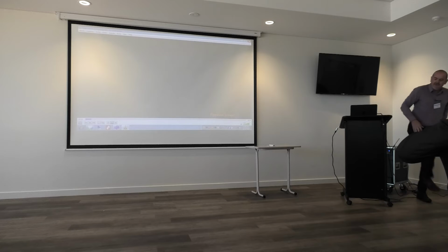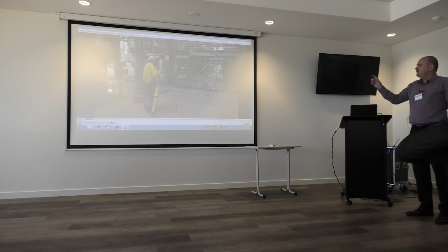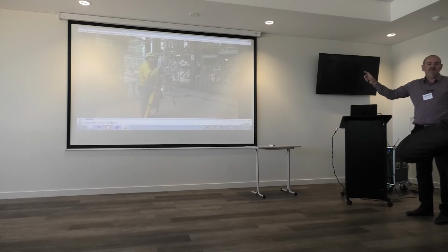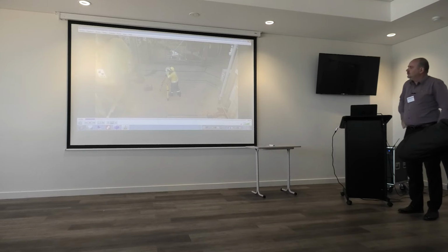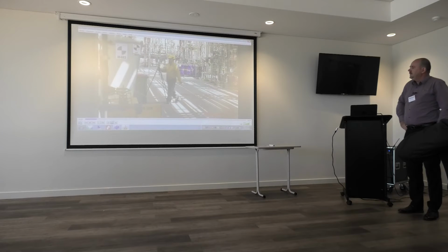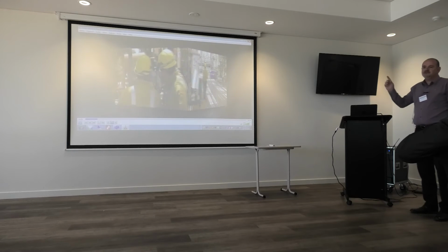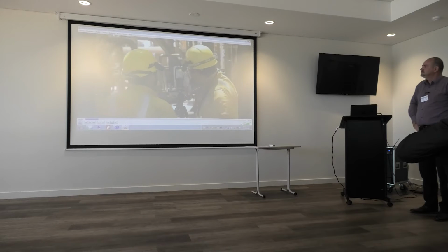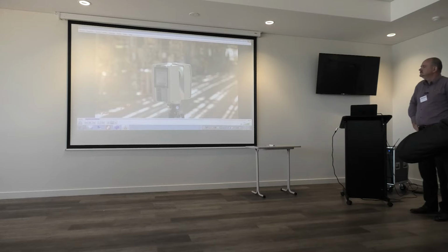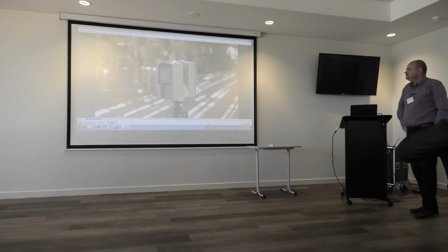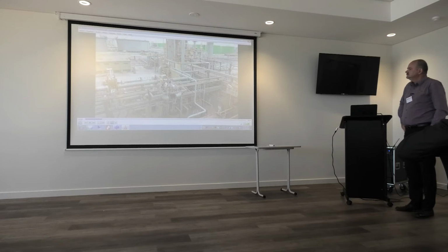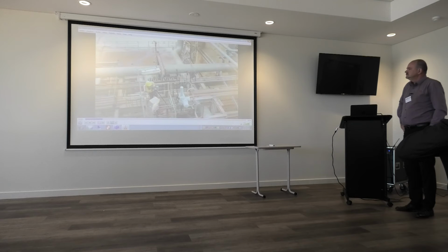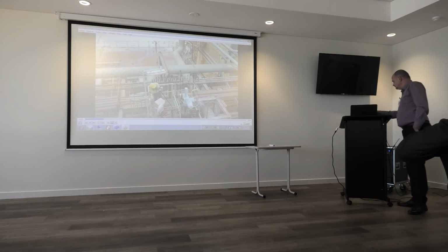So what he's doing here, he's creating a survey map of the area. This has been done down at the BP refinery. They set some context points into survey points. Survey practice. Laser scanning. Then they set up a laser scanning system to capture the points in point form. These laser point clouds are later used in the reconstruction process for creating intelligent CAD models and photogrammetry models. Applus has many years of experience scanning as-built geometry using survey methods as well as laser scanning.